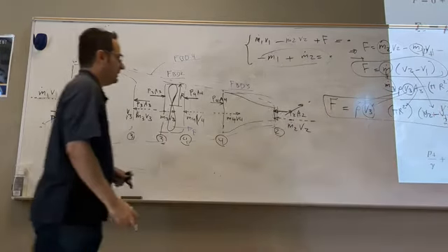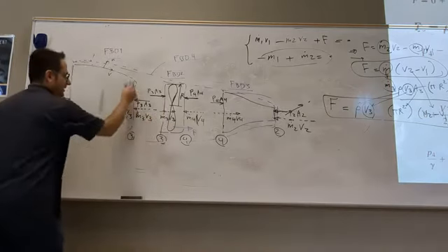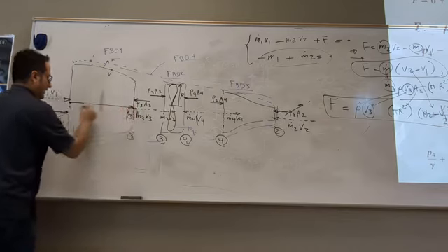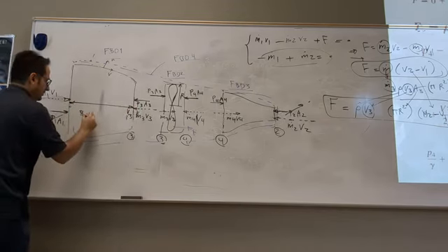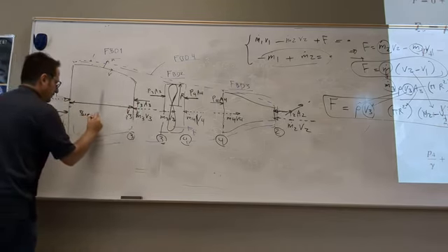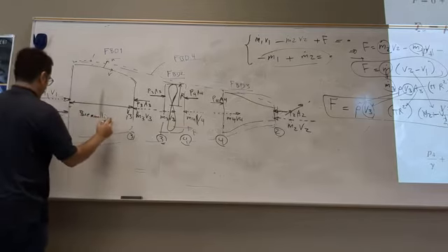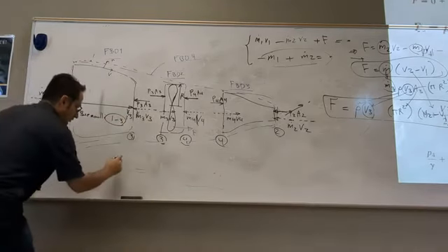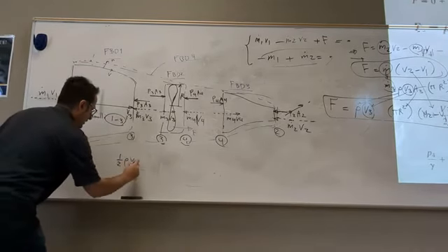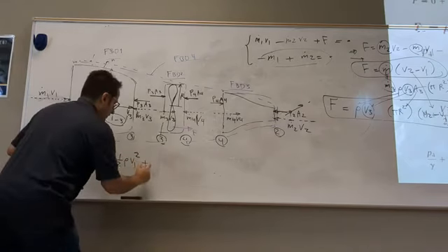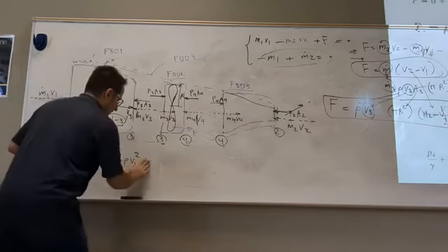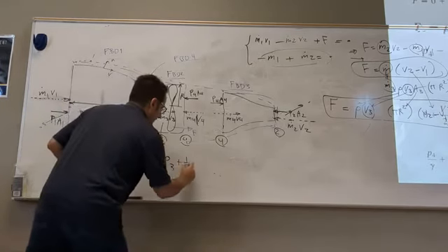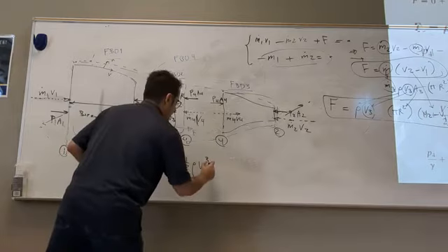What should I do? Well, I can take this system and write Bernoulli equation between these 2 points, as I said. Bernoulli between 1 and 3. What do I get? P at 1 is 0 plus 1/2 rho V1 square, plus there is no elevation difference, is equal to P3, which is non-zero, plus 1/2 of rho V3 square.